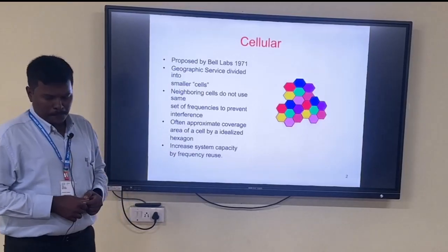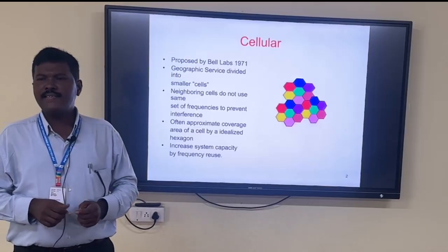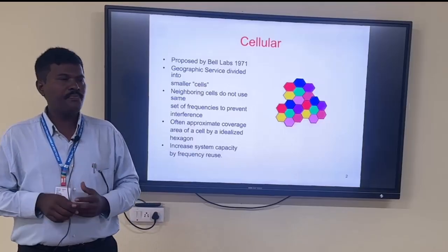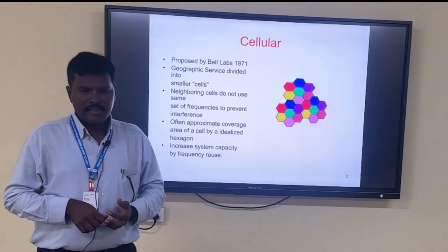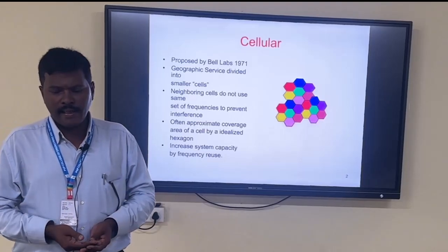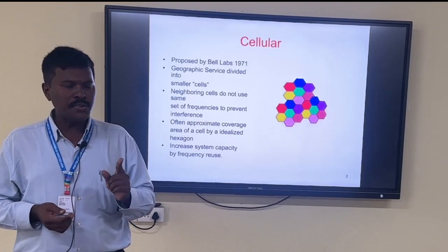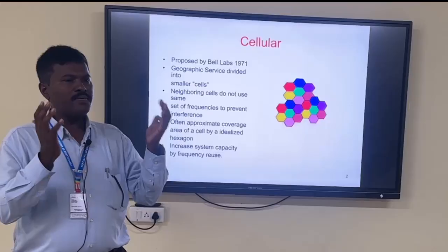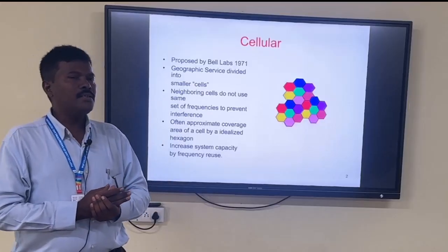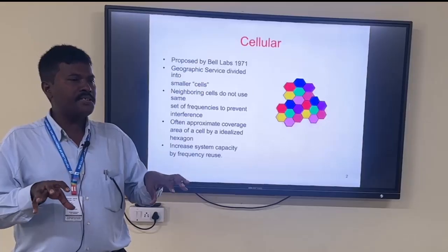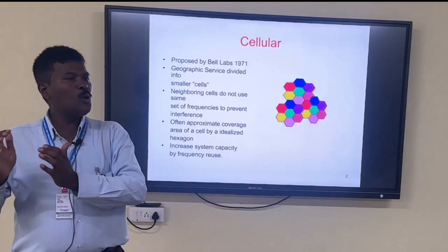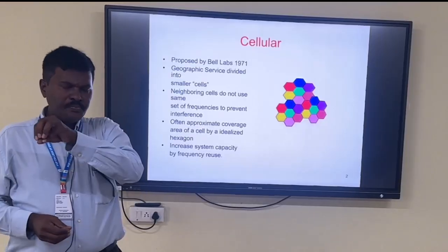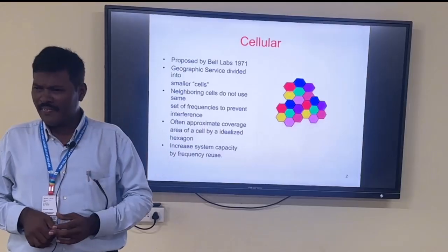Next, to increase the system capacity, there is the possibility of using frequency reuse. Where does this concept come in? As I told you, we can have a number of cells, but adjacent cells should not use the same frequency. So a group of cells we call a cluster. For that group of cells we have different frequencies, and some other group of cells can use the same frequencies used in the first group. That is called frequency reuse.